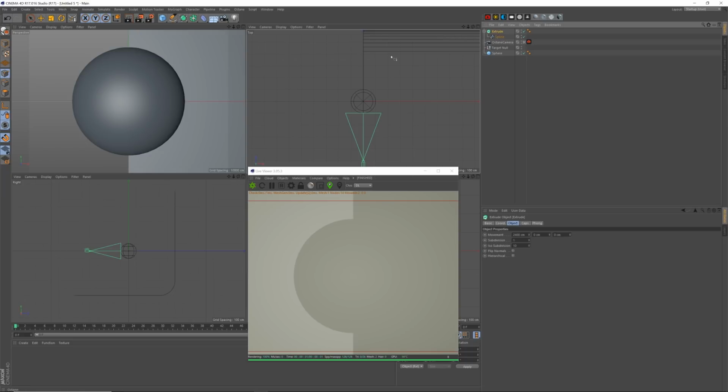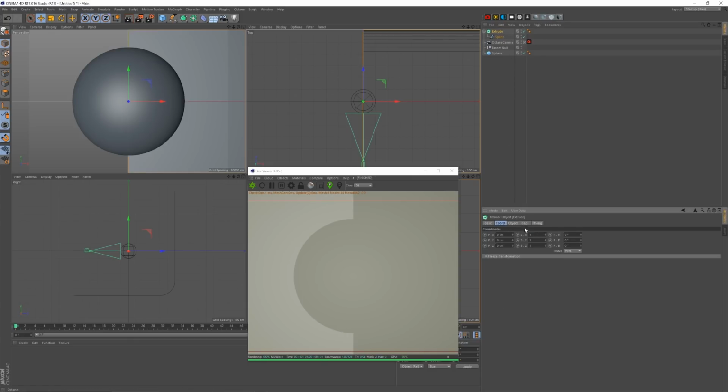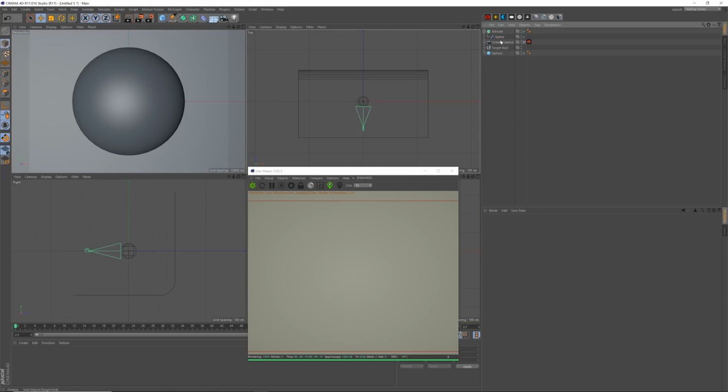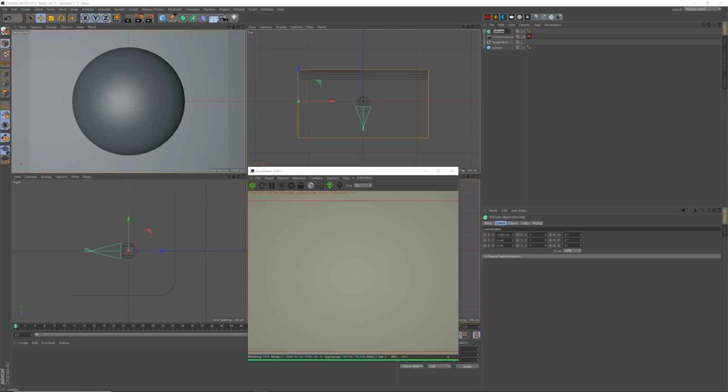And now I want to move the whole thing. Let me choose my model and move selection tool, but I can just select it, coordinates minus 1200. So now if I zoom out from this window, you can see it's placed exactly, it's centered in the middle of the object, which is exactly what we want. Great. I'm going to double click on that and rename it Cyclo.